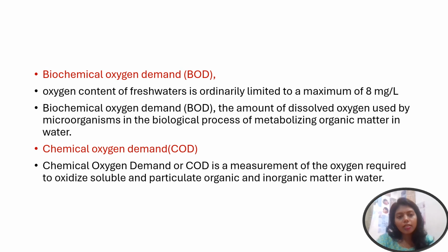So BOD and COD are two important critical parameters in wastewater since they measure the amount of organic matter that is present in the water, which impacts the efficiency of wastewater treatment and also the health of the environment. BOD is biochemical oxygen demand, that is the amount of dissolved oxygen used by microbes for metabolizing organic matter that is present in the water.